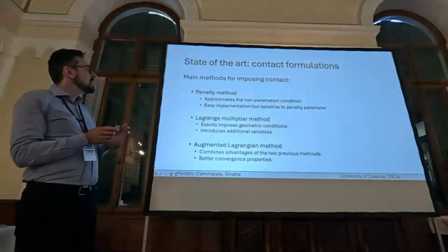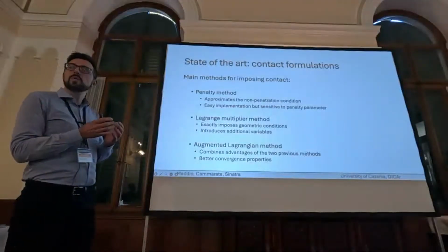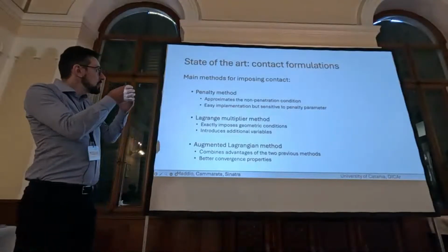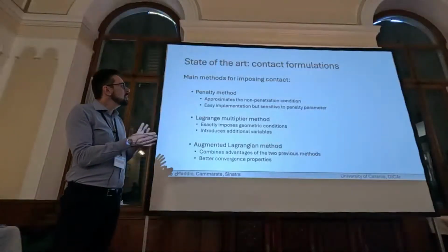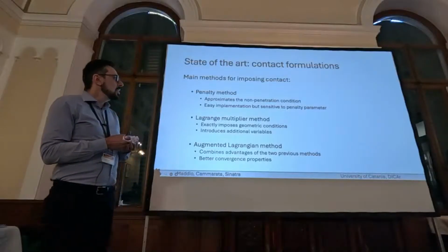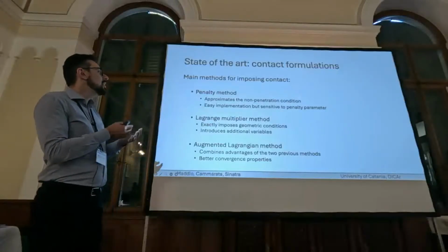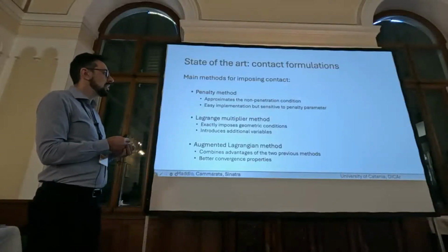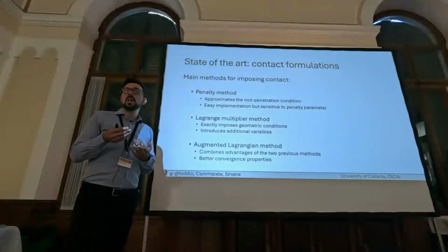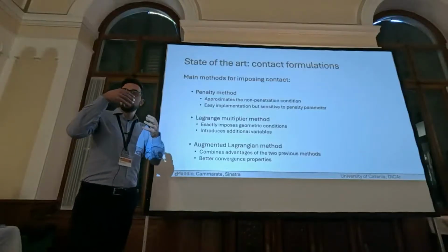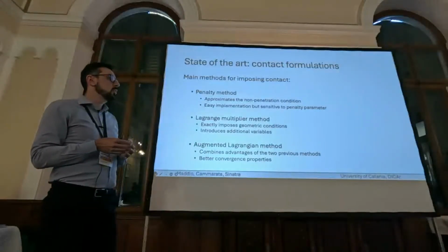Let's start with a brief introduction of the state of the art of contact formulations that are very close to ours. The main methods for imposing contact are, in this case, the penalty method. Here we approximate the non-penetration condition, and we will focus on this method because ours is based on it. It's very easy to implement, but it's sensitive to the penalty parameter, because lower values generate unphysical conditions, while very high values produce numerical instability.